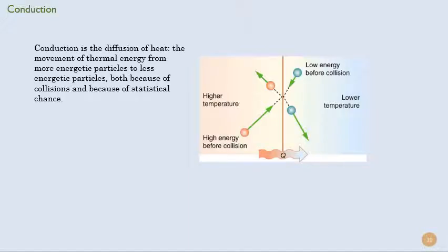Conduction is the one we're perhaps more familiar with. When we talked about thermal equilibrium, we were really talking in terms of conduction. When you have a higher temperature area, like over here, your molecules are moving faster, have more kinetic energy, and they might collide with the molecules from a lower energy part of your system, and they're going to transfer momentum.